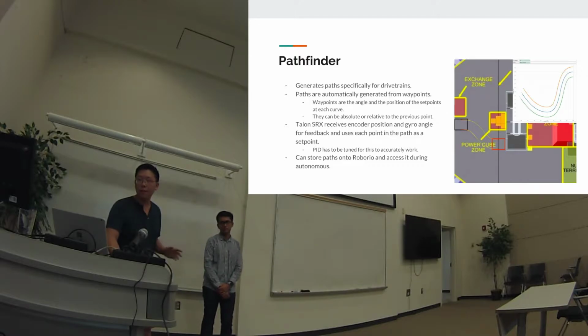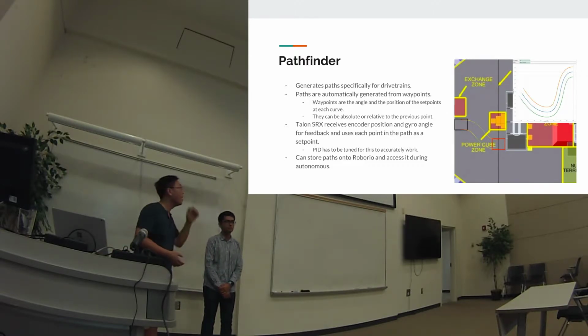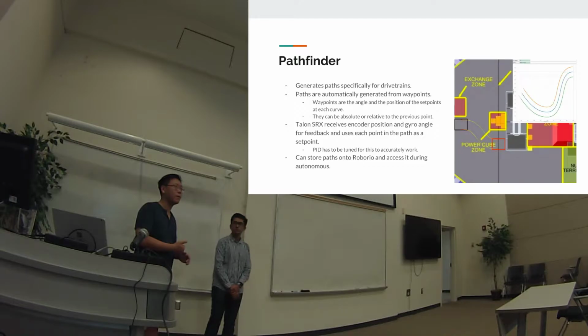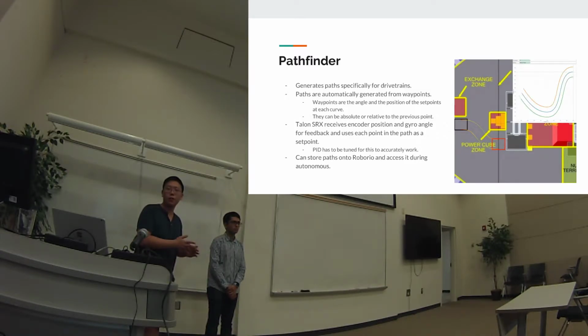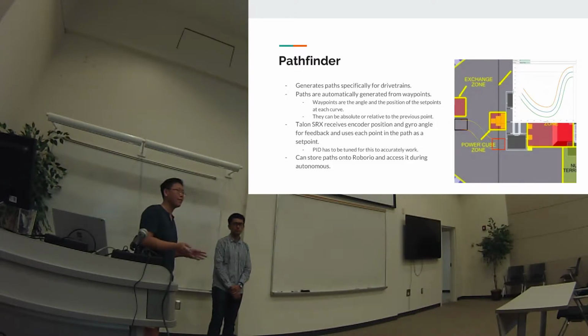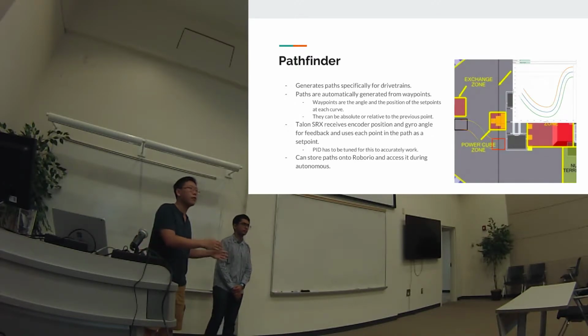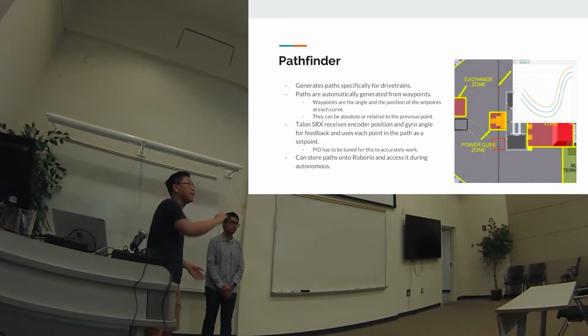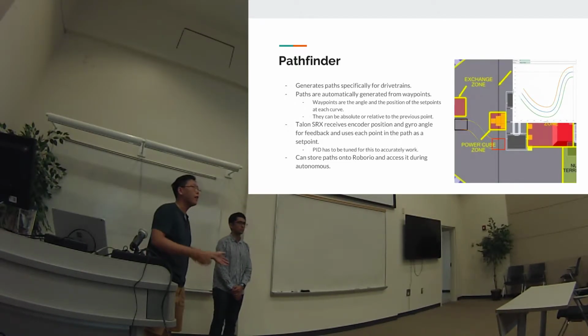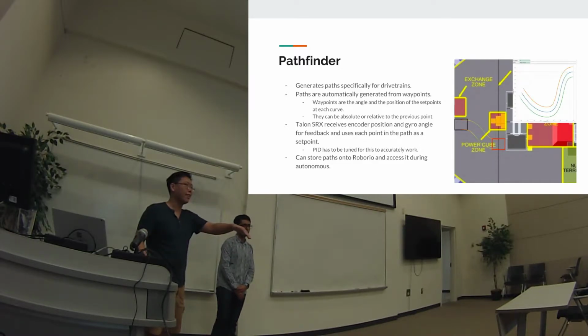And then one more thing about Pathfinder is that they had issues before. One of the big ones we found was that you can't drive backwards. There's a problem with the generation of driving backwards for some reason. There's ways to fix that for Pathfinder 1.0. Also, Pathfinder kind of violates some of the acceleration rules, because if you drive and then make a wide turn, for example, in order to do that turn, your right side of the drivetrain actually has to go faster than your left side, right? And because of that, it violates the acceleration of your right side. Yeah, it's kind of weird.